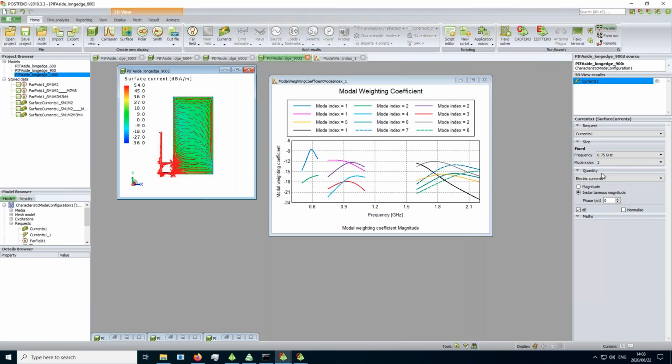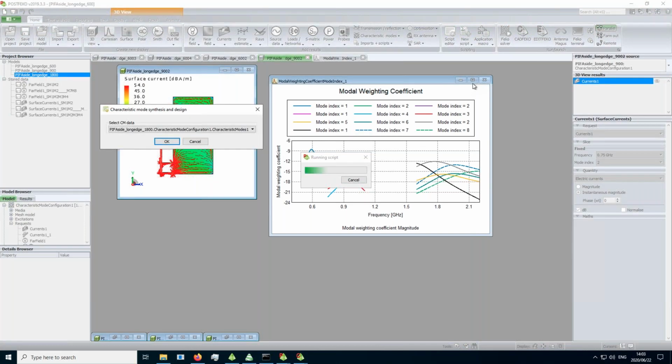Okay, so now we're at this point where we have 3 different antennas. We can see some behavior that we have some explanations for, but it's quite difficult to go from seeing these graphs to actually having a comprehension of your actual behavior. And certainly when we come to a multi-mode environment like in the higher frequency band. So we have another application macro that we can use for this, which is called the CMA synthesis tool. This is also available for download on the Altair Connect website.